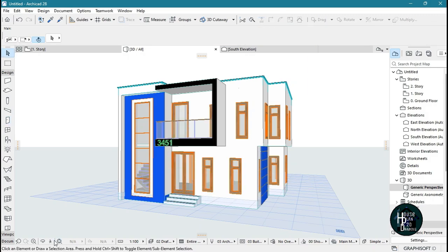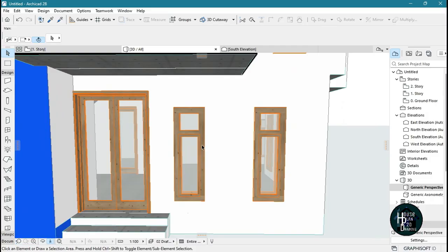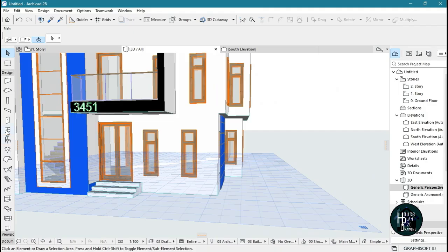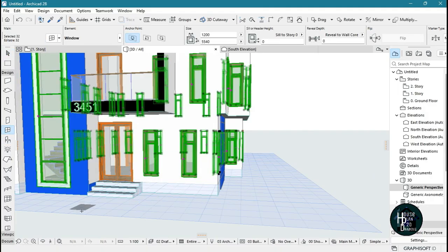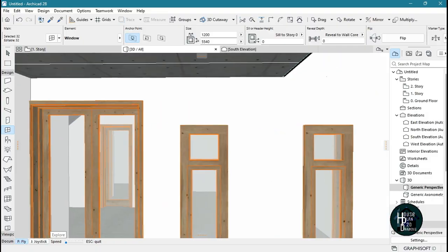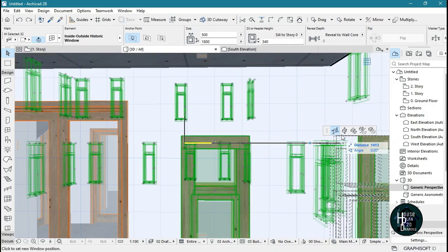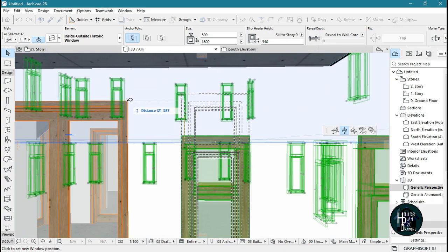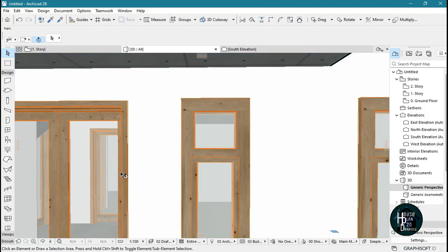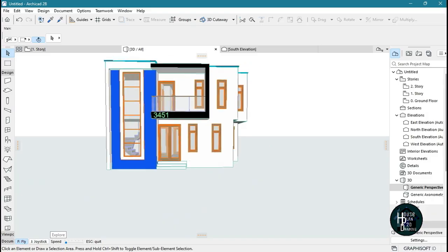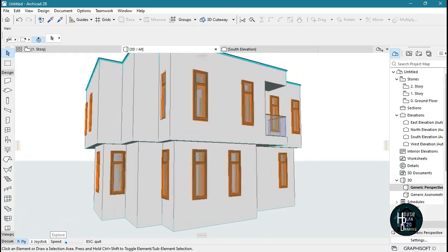You can also change the window height by going to the window tool here, clicking on the window tool, pressing Ctrl A, and zooming in properly so that we can adjust it to be at the same length. Pick this node, select the elevate and move it to elevate properly at this side here. Once you click on it, it's going to come outside and be at the same height as the doors for all of your drawings, as you can see.